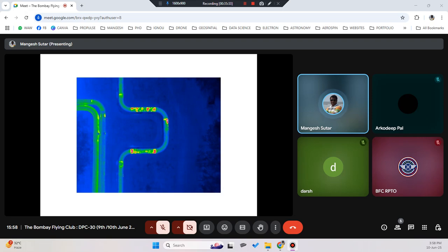A lot of times you hear in the news that at some location, like Ghatkopar area or any Powai location, the pipeline burst. Okay, why does this happen? Because there is water flowing inside continuously, and because of the water, the pipe corrodes from inside over a period of time, and slowly that corrosion becomes bigger and bigger, and one day it bursts.